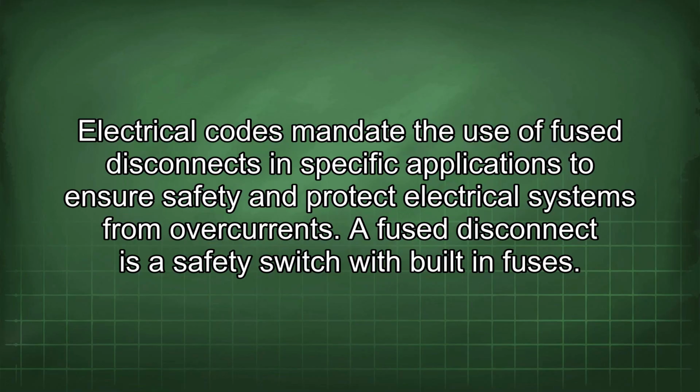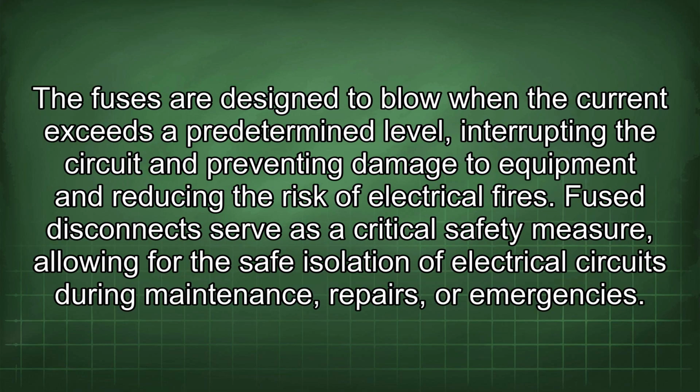Electrical codes mandate the use of fuse disconnects in specific applications to ensure safety and protect electrical systems from overcurrents. A fuse disconnect is a safety switch with built-in fuses. Fuses are designed to blow when the current exceeds a predetermined level, interrupting the circuit and preventing damage to equipment and reducing the risk of electrical fires.